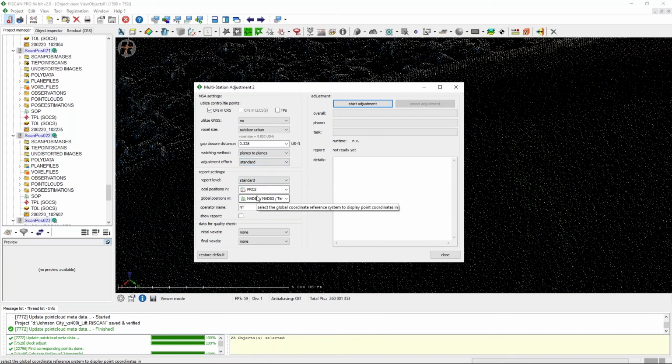Report. Oh, I didn't go over this earlier, and I'm sorry. I didn't think I had time, and it wasn't really important for me to put it into a PowerPoint. Standard report level, we'll go over that another day. But you can choose what kind of report level you want, right? If you have a full report, I recommend that, because it gives you how many planes they found, the matching planes, the accuracy, the standard deviation of the planes, so how well everything sits together, and then also down to the survey control, GPS information. All the information from the scan data from each scan position is stored into the report, and we'll do that in another PowerPoint. I just didn't think I had time today.